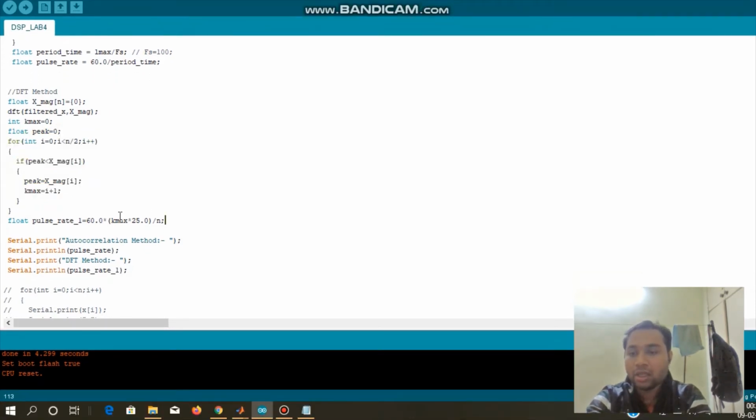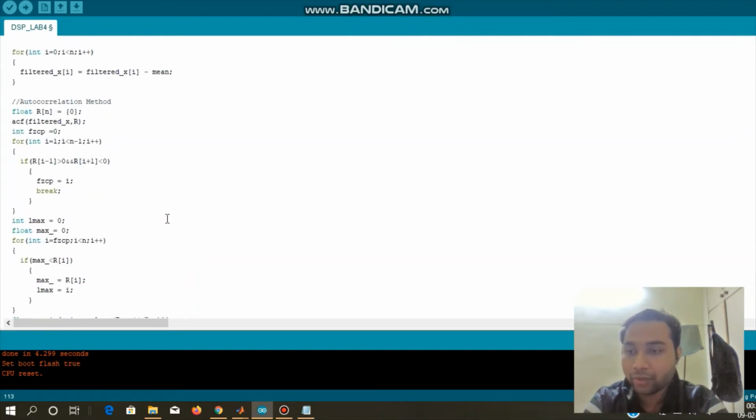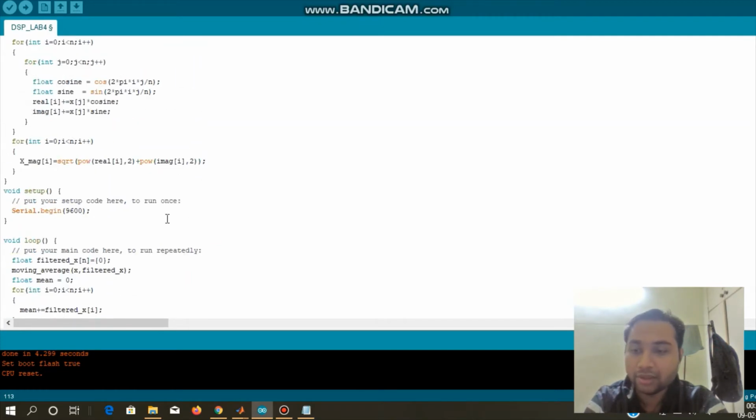So from that we can use a pulse rate implementation, that is, for 1 minute, that is 60 seconds, into kmax into the sampling frequency, that is fs, divided by the total number of samples that we have taken in our domain. So straightforward. Now we are going to implement and see the results.